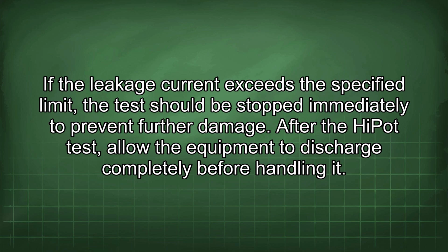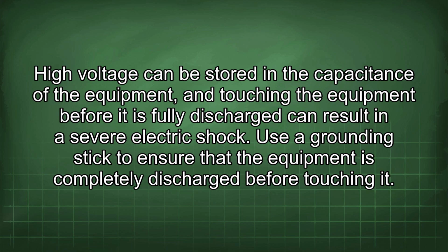After the HiPot test, allow the equipment to discharge completely before handling it. High voltage can be stored in the capacitance of the equipment, and touching the equipment before it is fully discharged can result in a severe electric shock. Use a grounding stick to ensure that the equipment is completely discharged before touching it.